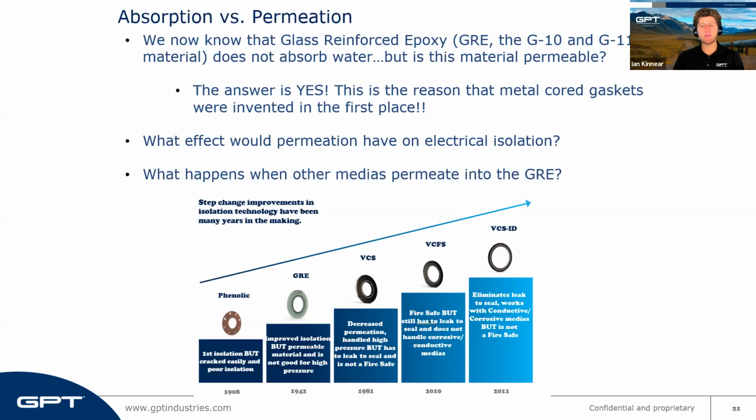And in addition, many times at these high pressures, we're dealing with other medias than water. So if you have other medias that could be a little nasty, H2S, CO2, whatever it is, this is a little off branch to the water topic, and they're being driven into the GRE, we could actually start breaking bonds and having some chemical compatibility issues. So it's just something to be aware of.